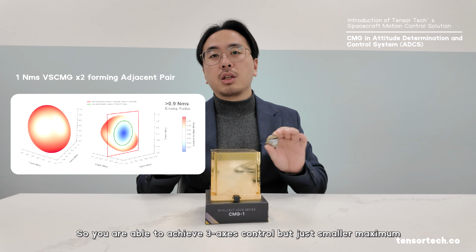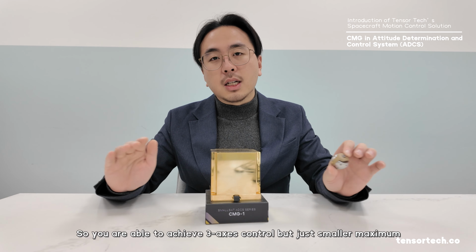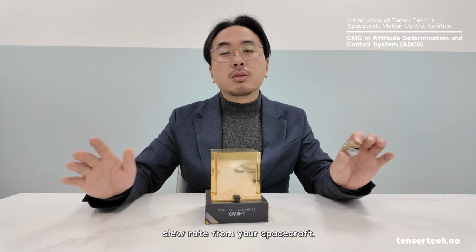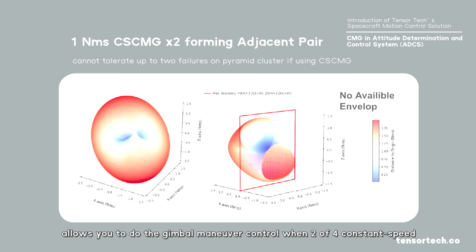So you are still able to achieve 3-axis control, but with a smaller maximum slew rate from your spacecraft. However, that's not the case for constant speed CMG that only allows the user to do gimbal maneuver control.